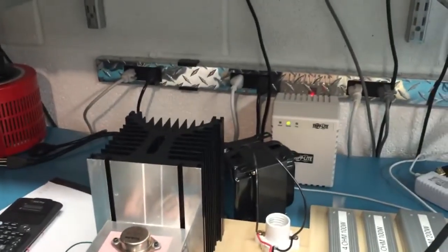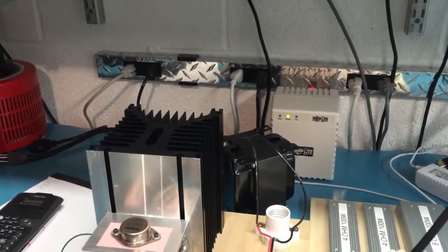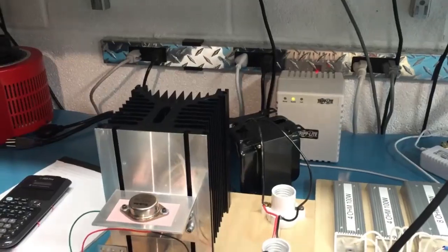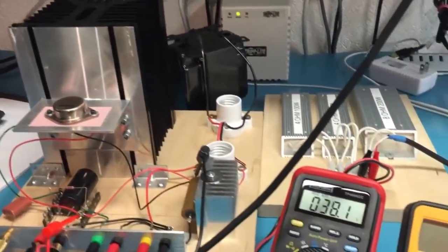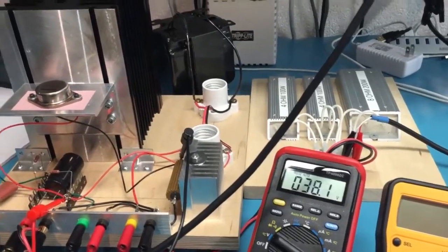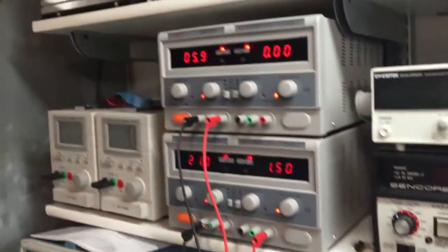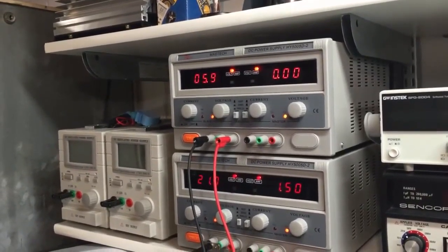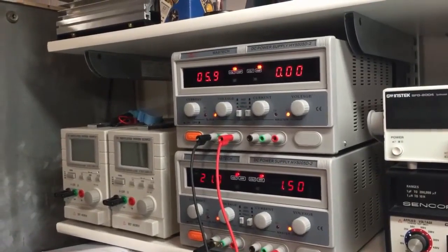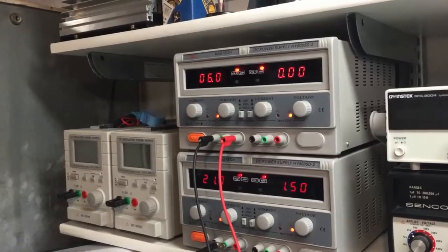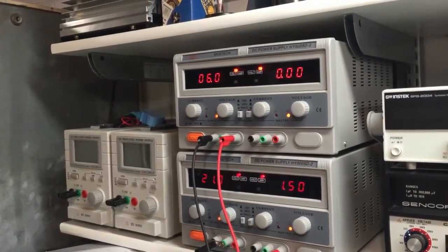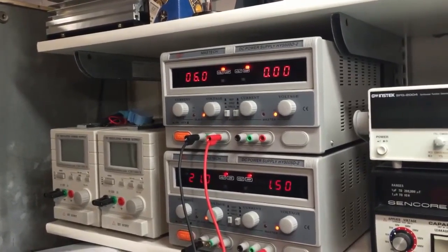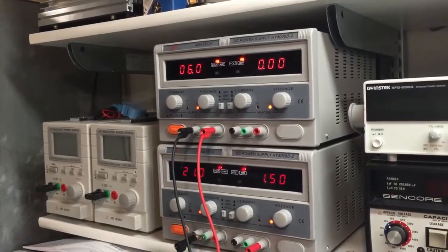You can see I've got the Hammond 193V inductor wired in place of the light bulbs, and the operating point is about 38.2 volts, and if we go up here it's about 1.5 amps, and the total power supply voltage is 42 volts, and the gate to source voltage looks like about 6 volts plus, or minus I guess, the 1.5 volts that I'm dropping across the 1 ohm source resistor, so 7.5 volts.